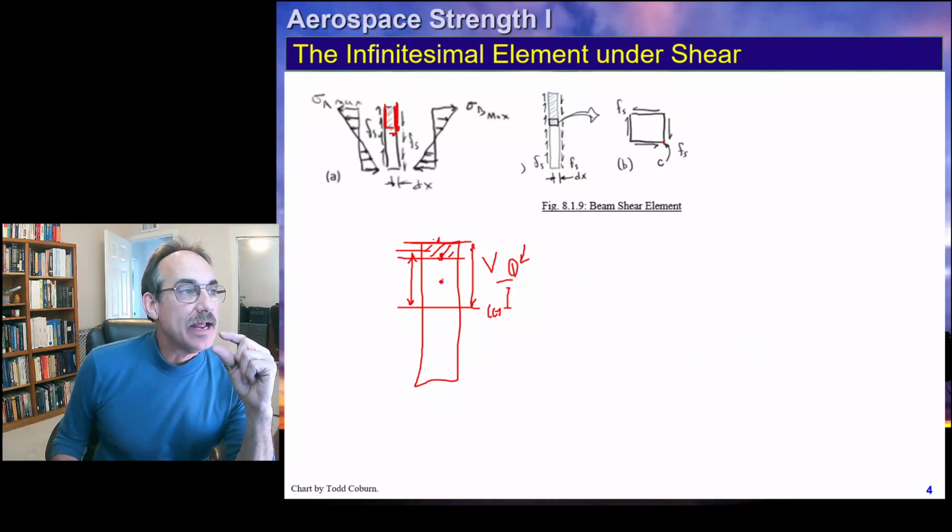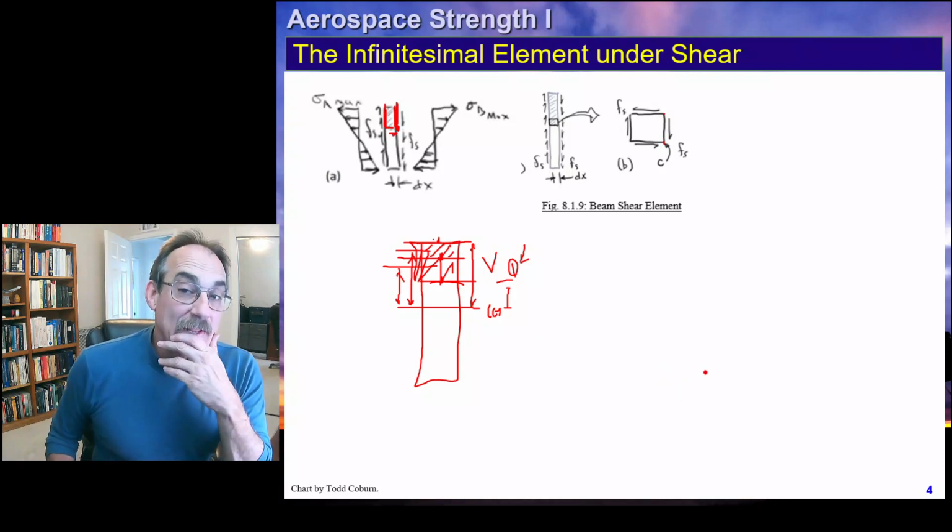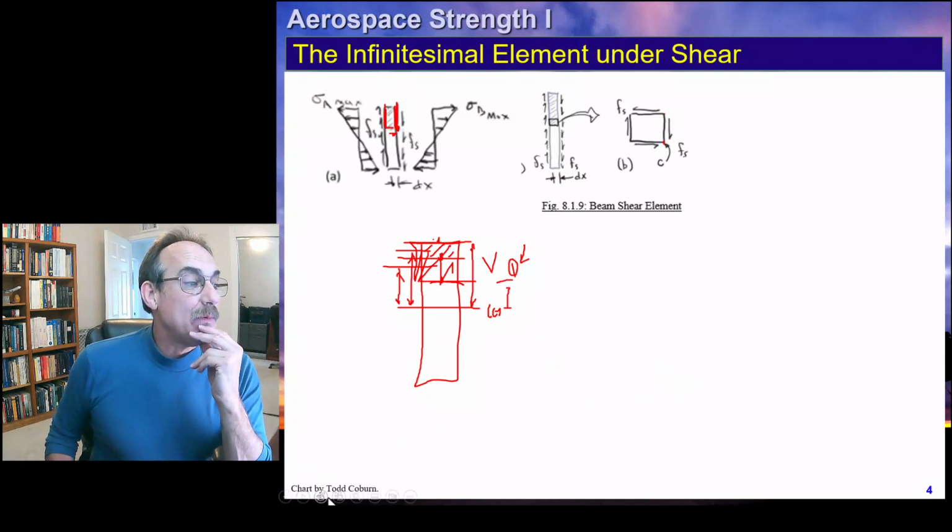If we want the shear down here, we draw a line parallel to the CG, and we shade everything above it. Now it's this total dimension, this length, times this thickness, times the distance to the middle of that slice from the centroidal axis. That's how we calculate Q.